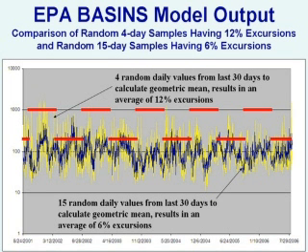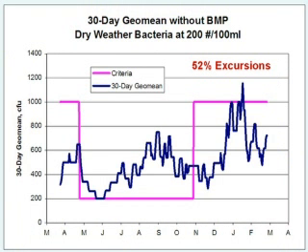So in this case, we're always below the standard. The 90 percentile geometric mean is below the standard, but there are more excursions at the upper end and the lower end, and those are the ones you might want to concentrate on. But it may be that you're only using the water in the lower ends. In the upper ends, you're not so concerned about the use, and thus you might set up your site-specific requirements for CSO treatment based upon analysis like this.